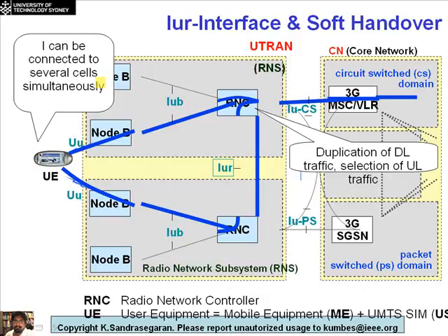There's a concept called macro diversity, and there's also a concept called micro diversity. Two important concepts in the context of wideband CDMA. Anybody knows what they are? Now in wideband CDMA, a mobile can be communicating with a number of base stations simultaneously.